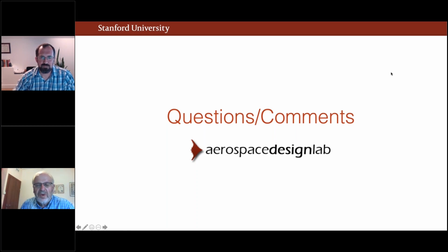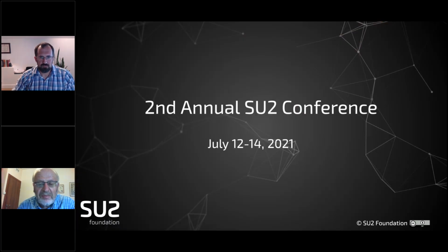There were two questions raised, one by Matteo Pini. Thanks for the very informative presentation. Great work and kudos to all the teams. Just one question. Are high-order numerical models also available for solving incompressible flows? I guess it means not only high order, but the LES methods. That's a very good question. I don't believe that the wall-modeled LES and hybrid RANS-LES methods are in the incompressible flow solver at the moment.